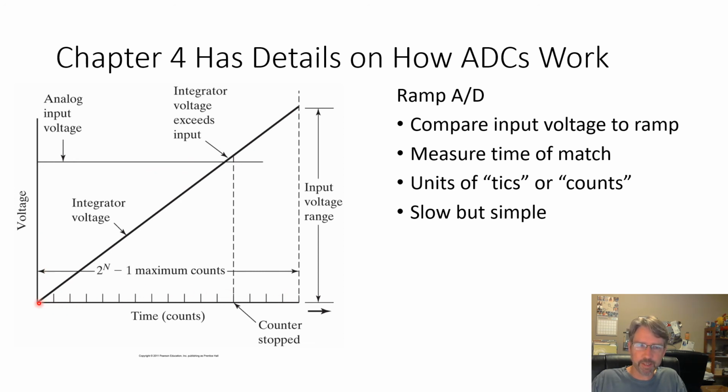There's a circuit in the analog to digital converter that ramps at a known rate, goes from 0 up to the maximum. And there's another circuit that compares this to the ramp, and when they match, it sets a flag, it notifies things. And so you start a stopwatch and you wait until these match, and then knowing the time lets you know the voltage.